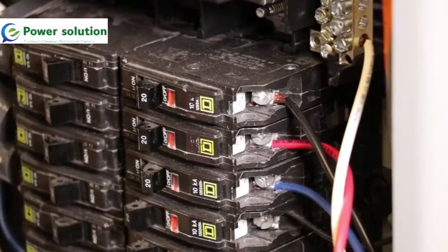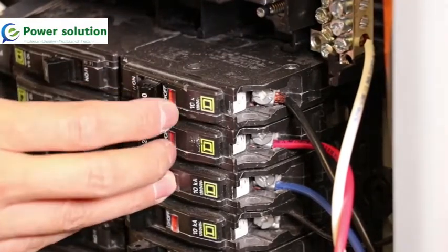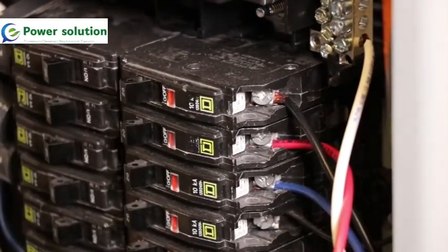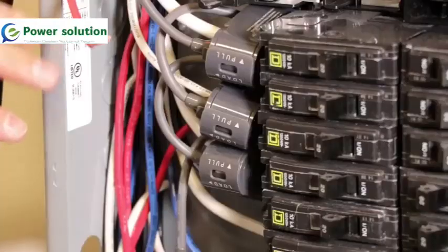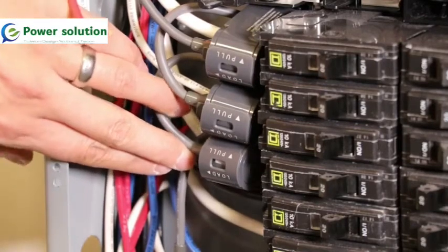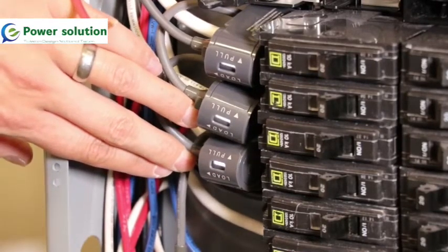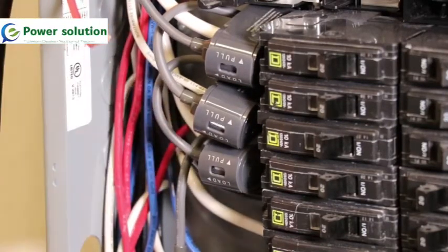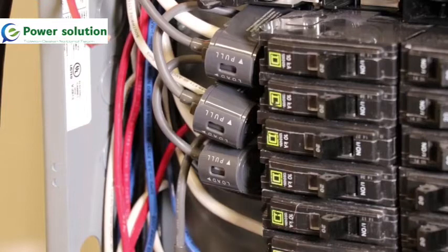Once the unit is secured onto the panel, we can power on the phases that activate it so that we can boot up the system. On startup, the CTs on your chain will begin rapidly blinking. That's an indication that they're running their self-test. As long as all the CT lights shut off, the system has passed its check and it's ready to go.